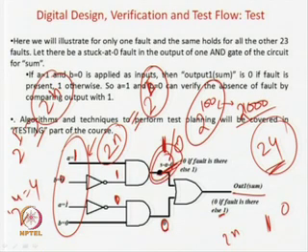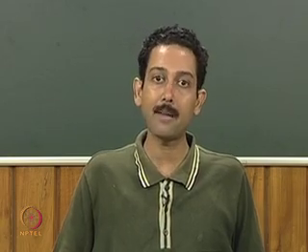You have to give faults at all the points in the circuit, and then you have to find out automatically, by using tools, which patterns you have to apply. And you will also surprisingly see that this 2n will actually come to a very low level, even hundreds or less, because many of the structural faults are equivalent, and the same pattern can detect multiple faults.